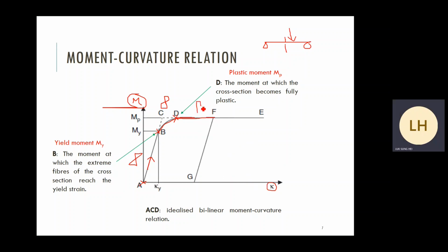This is how a beam section evolves under gradually increasing loading. There is a dashed line linking point B and point D. Same assumption: quite often for our analysis, we don't want to consider any nonlinear behavior. So we artificially extend this straight line to point C. Adopt the so-called bilinear model again.